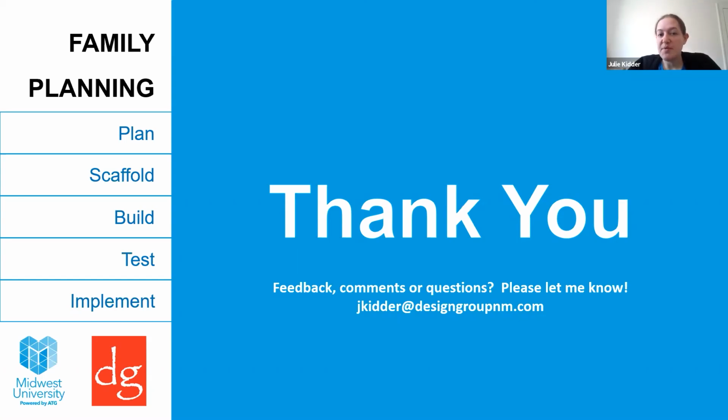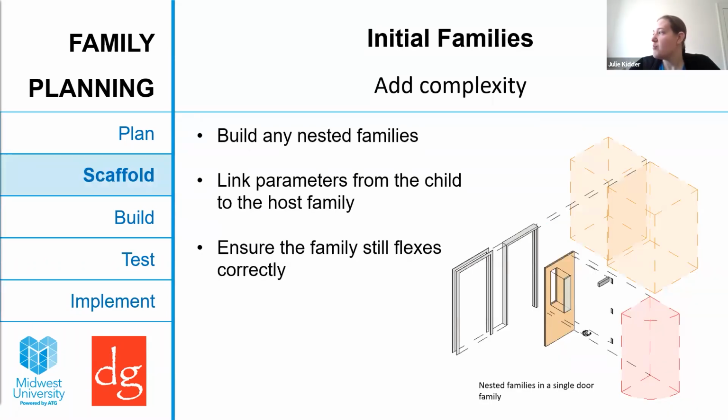How do you determine whether you integrate into the main family model or a nested model? Generally, the host model doesn't have anything that is just in the host model. Everything that is in it is a nested family. Let me go back quickly to the one showing them pulled apart.